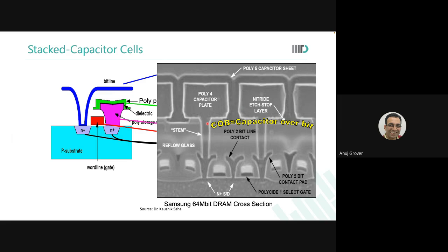Okay? And that concept is used over here, in the previous slide, to say that I will use multiple fins to increase the capacitance. Fractals are one of the most efficient ways to implement very high values of capacitance on chips. Okay? So just looking at this particular device and what it means.